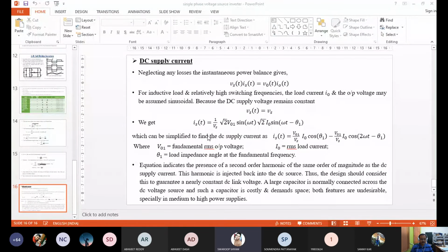Sir, we are calculating delta Q from the graph of IC and time. Yes. That is the charge enclosed. Over one cycle, the average charge enclosed will be 0. Average voltage across the capacitor is constant. So that means, sir, we can take either the part below the x-axis or above. So which one is easier? We are taking that. Yes.